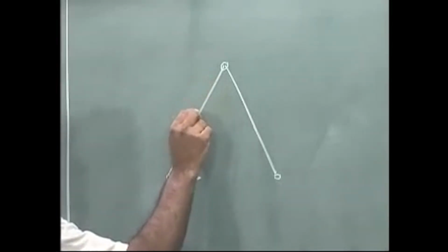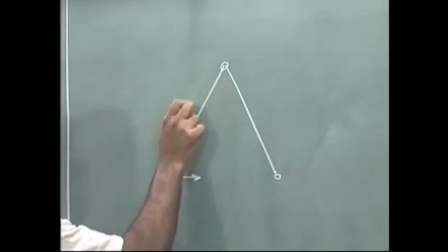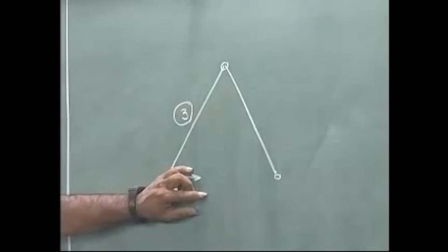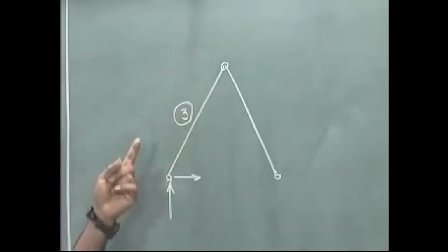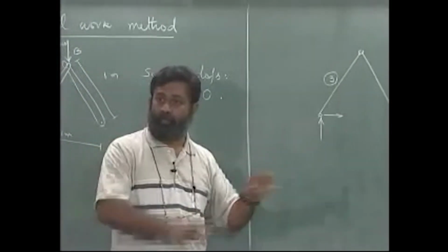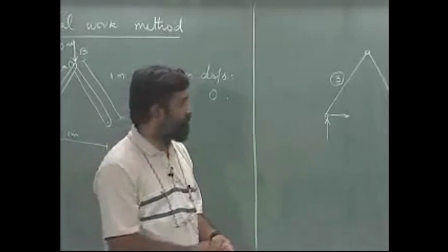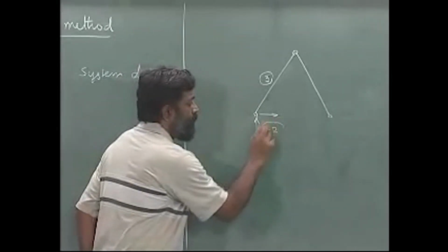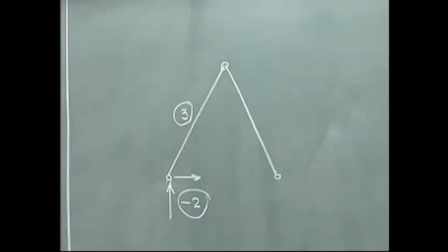Individually this particular rigid body has 3 degrees of freedom, meaning it can move without bothering about any of the other constraints. This can move with 3 degrees of freedom. This is something that we know, and I am just talking about the planar rigid body here. So, I have minus 2 over here because there are 2 that are lost by fixing.